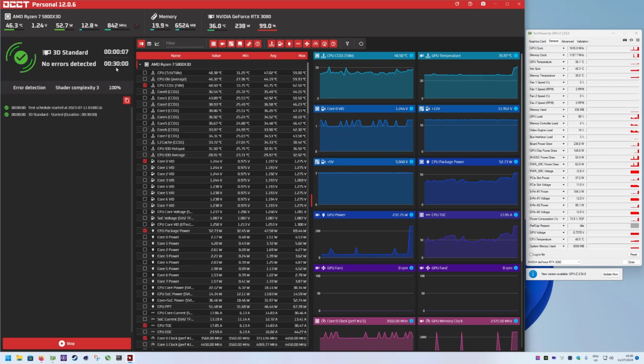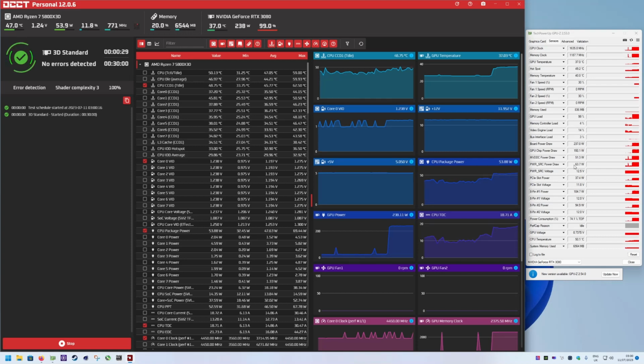It runs for 30 minutes at a time, and it shows you on the left hand side here basically what it's doing. Whilst it's doing that, you can monitor with GPU-Z, obviously the core clock, I said 1635, GPU temperature 36, that's the core temperature, hotspot, the hottest part on the graphics card, 49, and the memory temperature is at 40 degrees. Total power draw for the graphics card is 240 watts roughly. 150 of that is from the PCIe cable, that's what GPU chip power draw means. And then PCIe slot is 37, that's from the actual slot on the motherboard that it's drawing.